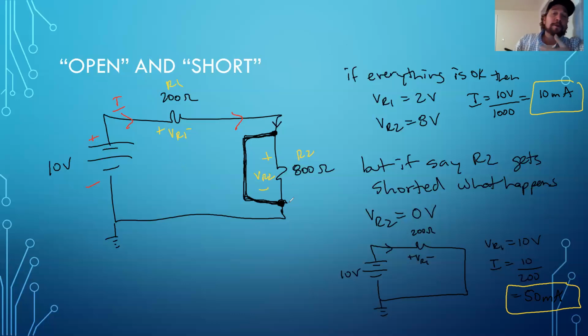All right, when we start talking about parallel circuits, we'll be able to show mathematically that what I said here about the electrons choosing this path that has no resistance over the path that has 800 ohms is always the case. And it can be shown mathematically too that really this 800 ohms basically disappears if it gets shorted out.